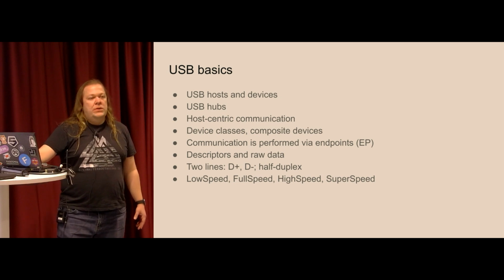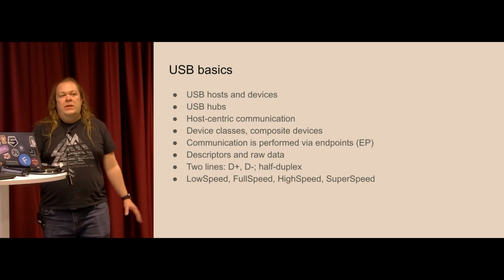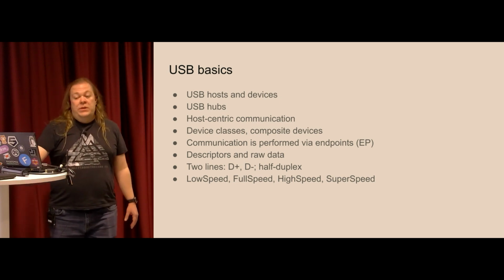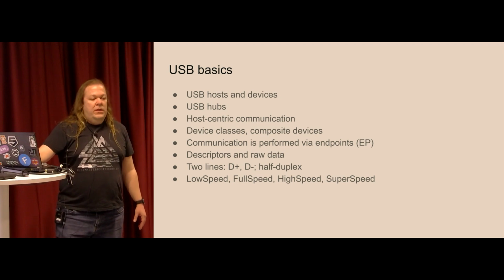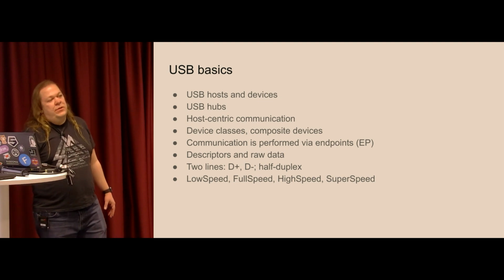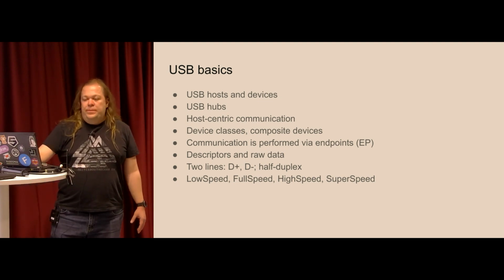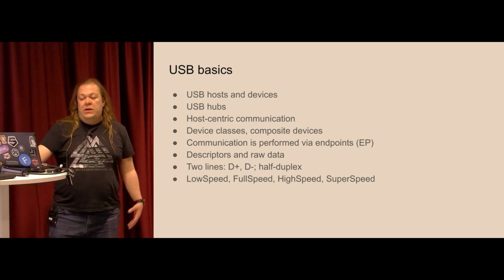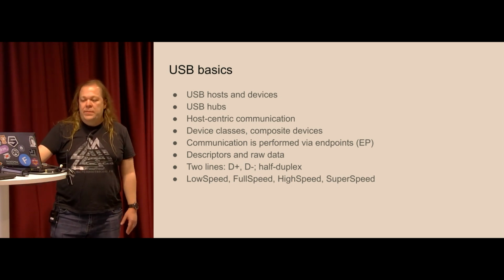Most USB devices communicate beforehand, over some generic protocols, what they do support, which is called a descriptor, and then when the host needs to communicate to the device, it uses data of a known protocol, and it doesn't have to support complex things like TLV or JSON or whatever else. So the descriptor basically tells what to expect from this device and how it is supposed to be used.